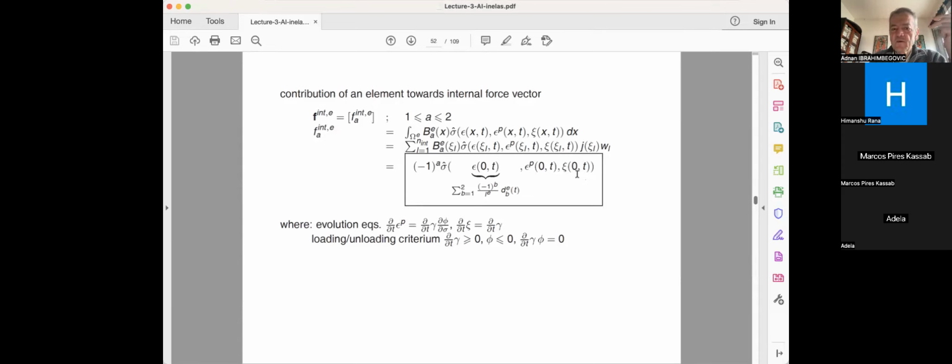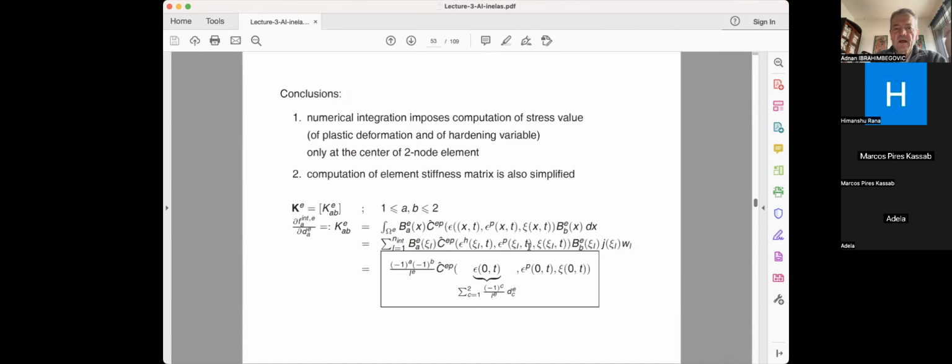How do you get these values? You get them from the evolution equation. Namely, you have to solve the plastic deformation dot equal to gamma dot times d phi d sigma, which is the sign of sigma, and xi dot equal to gamma dot. And this evolution has to be in agreement with gamma dot being positive, phi being negative, and gamma dot times phi equal to 0. So recall that we had evolution equations that are computed by the time integration schemes, and basically I have to do that, and maybe just one more remark before we go to this explanation of how you can actually compute it.